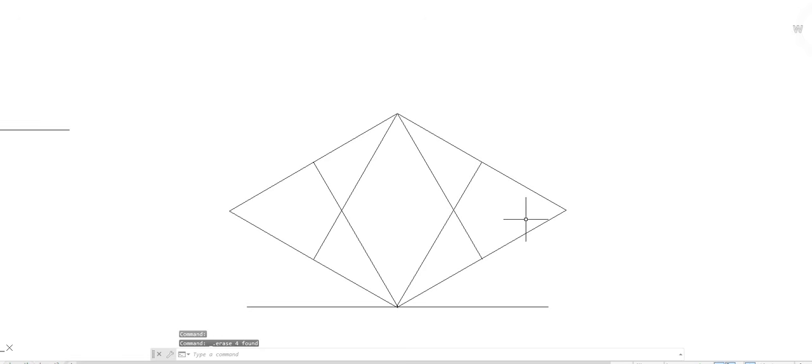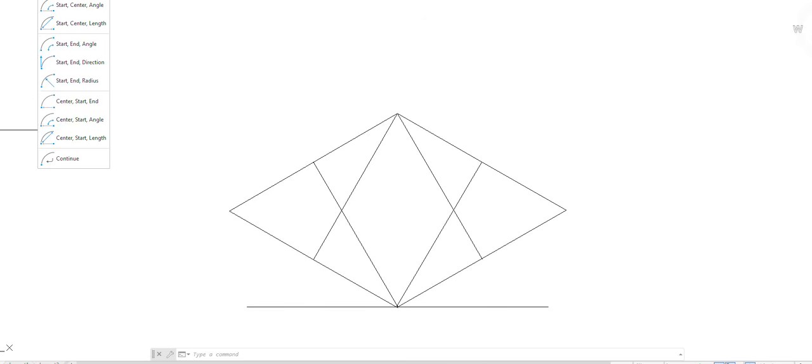So offset the rhombus and select these cross lines from these two closed corners to the opposite line's midpoint. Now you will draw a curve downwards. Select this line and offset it here. This is to show that there's a thread there. Now we'll just draw a line here based on the thread length, and you will offset this line.